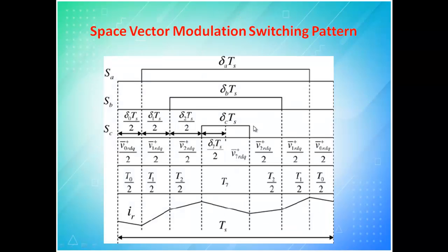So when you see here, this is how the pulse width is: maximum width, then reduced pulse width, then reduced pulse width, and these are the 3 for the top 3 thyristors. For the bottom 3 thyristors, they will just give the opposite of this. For example, thyristors 1, 2, 3, 4, 5, 6. For one, the previous leg is the third leg bottom. So for the third leg bottom, you will have pulse only in this portion as well as in this portion alone.